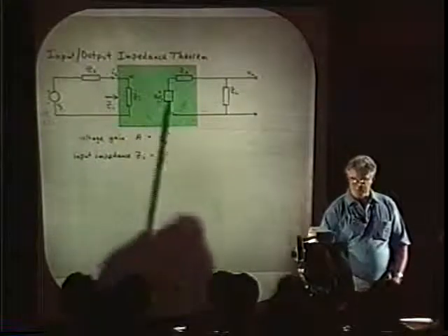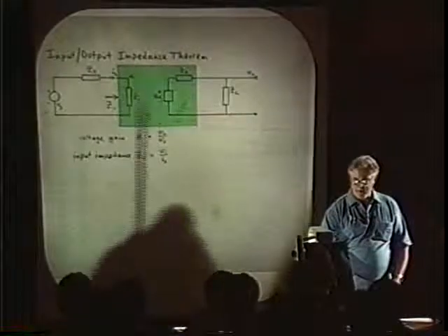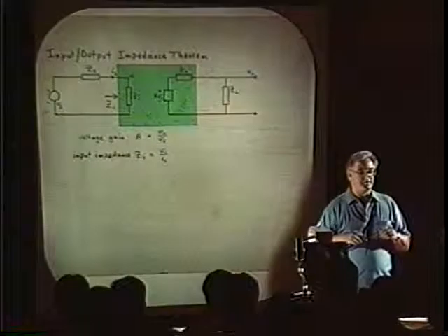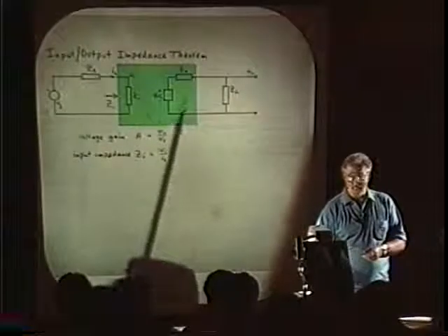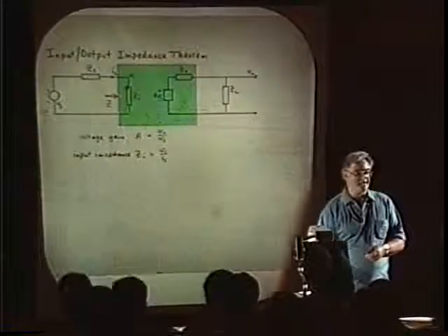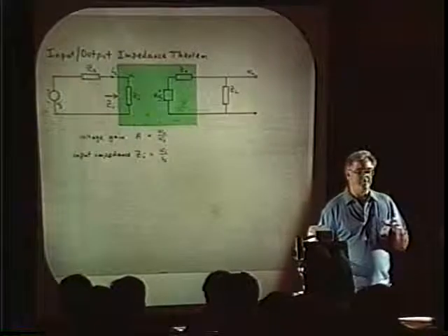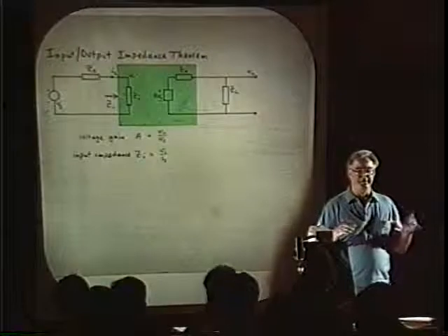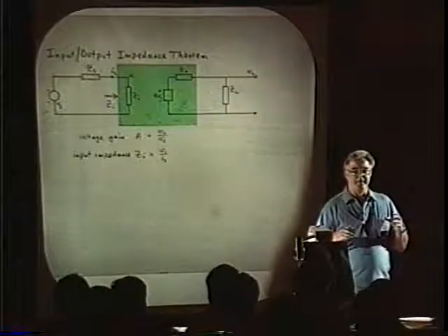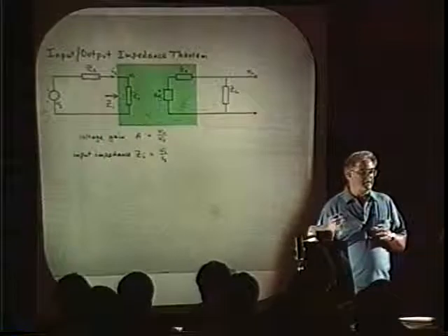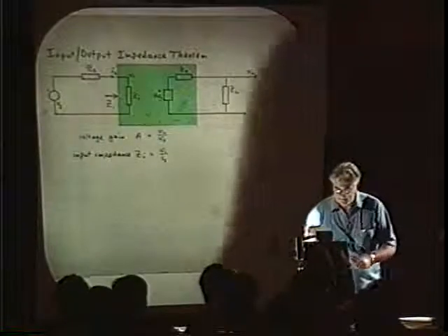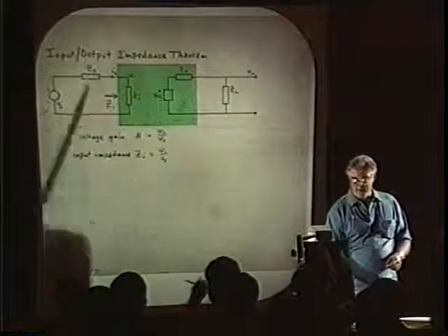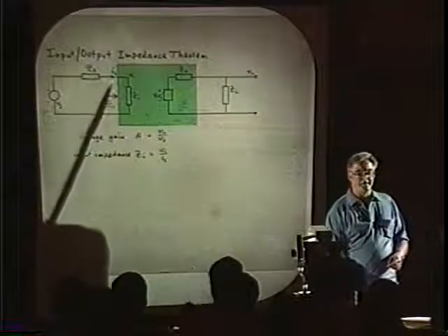Now remember, this is a block diagram representation. You don't know what these elements are. You have a detailed model with all the R's, L's, and C's and transistors in it. But the objective is to find ZI. That may not be obvious from your model, especially if there is feedback in the system. Because, you know, feedback modifies input and output impedances, and they are not the values that relate directly to circuit elements. So the ZI is the thing that you're trying to find by analysis, and you have to solve a transfer function to do it.